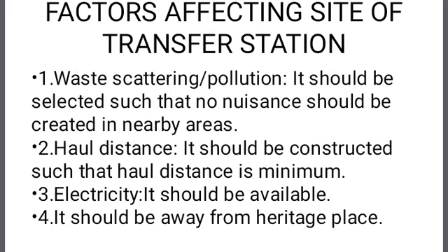Second, haul distance. The transfer station should be constructed such that the haul distance is minimum. It should be provided at a suitable distance away from the waste generation source. Third point, electricity.